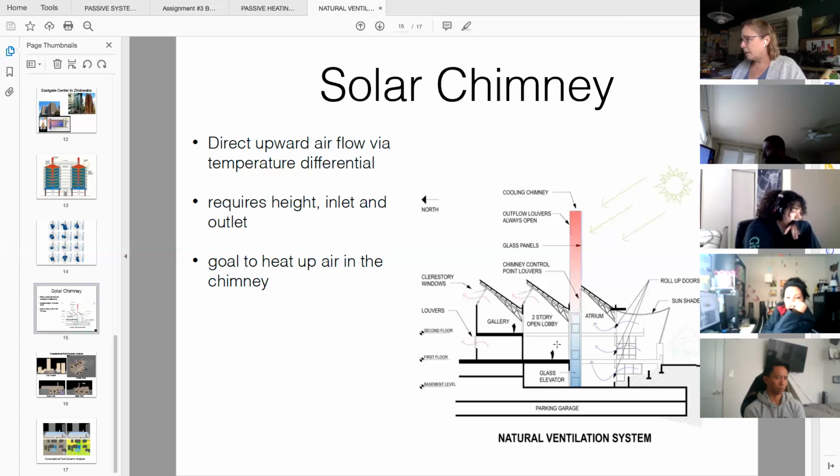So not ideal for being the sole natural ventilation part of the design. So on the north-facing side, within the clerestory windows, we added operable awning windows to also let heat out at the top of the building.